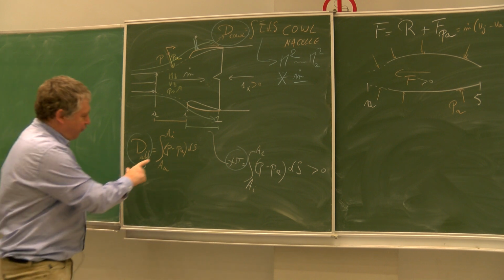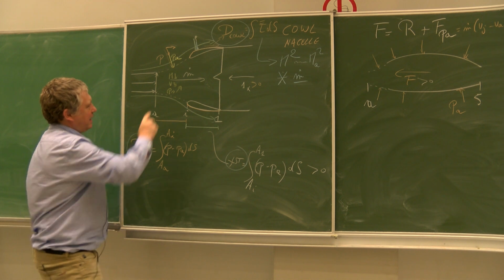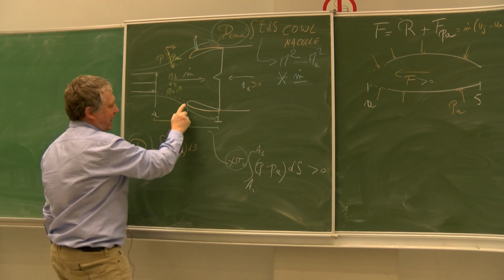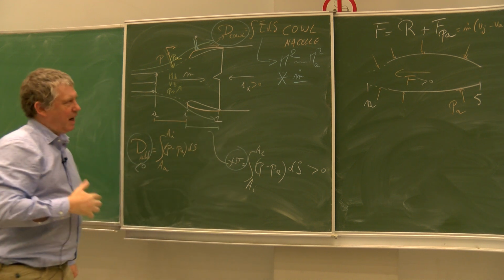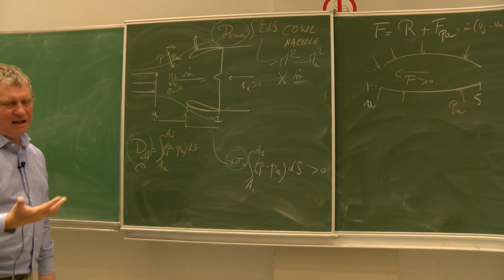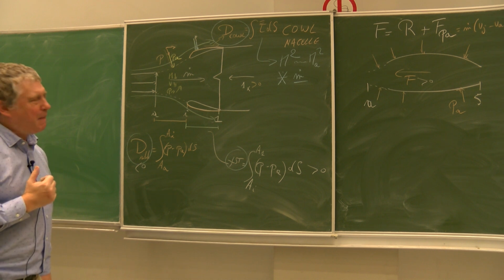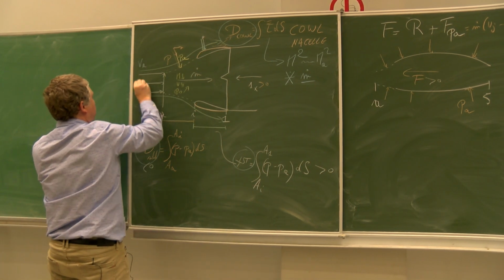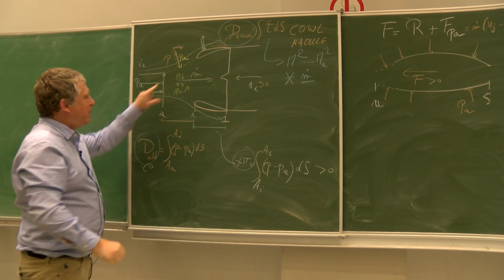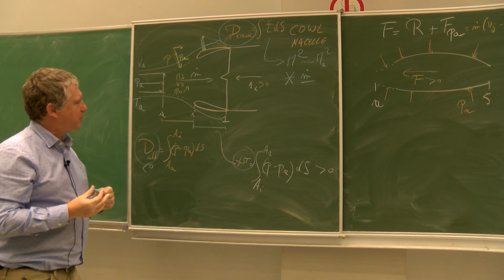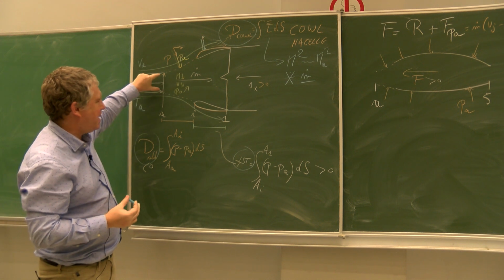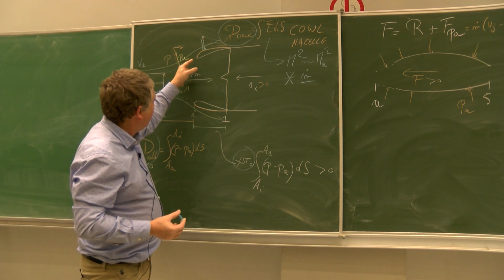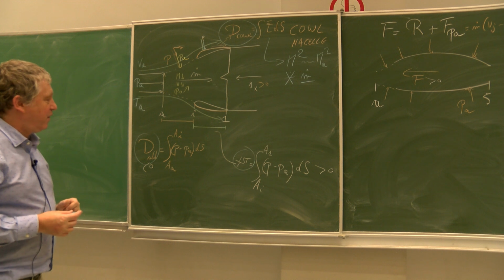Whereas for the pressure that you have here internally, so that you have on the streamline here externally, and the pressure that you have here, this will change depending on the mass flow rate, for a given VA, PA, TA, it will change with the value of m dot, because m dot will change the shape that you have here, and m dot will change the pressure here, and will change also the pressure that you will have on the other side.